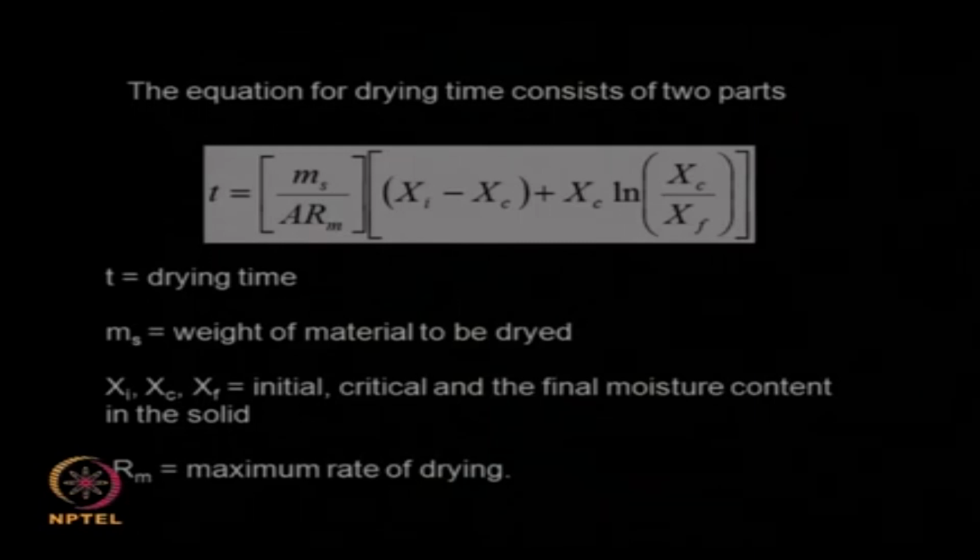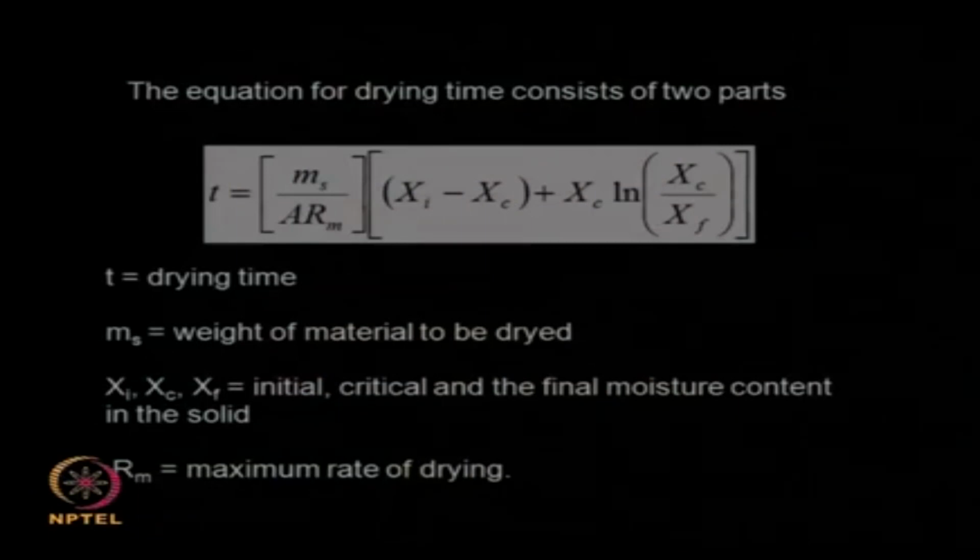So today we talked about drying, the most important downstream step for bringing the moisture level to a very low value, and it has a lot of advantages. You can use conduction type of drying, we can use convection type of drying. Generally we do not use radiation in biological systems. Then there is something called the equilibrium moisture content or the final moisture content, below which you cannot dry a material. So there are many equations which are available which can help you to calculate the entire drying process. So in the next class we will talk more about the drying phenomena.